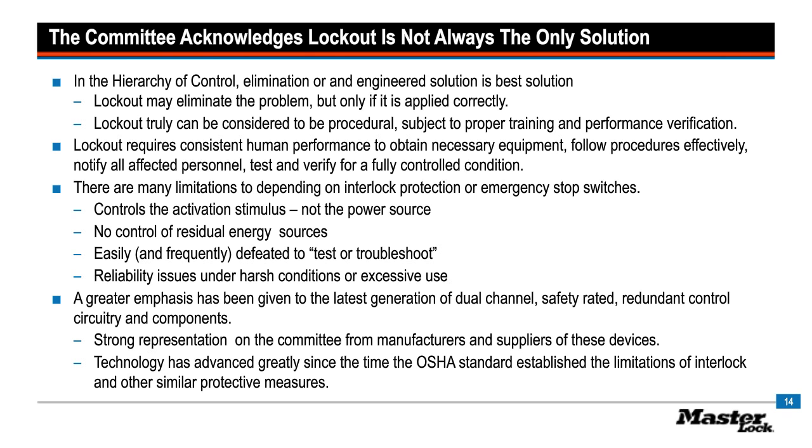So there are limitations certainly on depending on engineered controls, and there is great guidance on, again, the control reliable circuitry, dual channel, redundant safety sources to control not only signaling, but energy isolation points. For instance, the current high-tech guarding out there, when it is triggered, it opens disconnects.